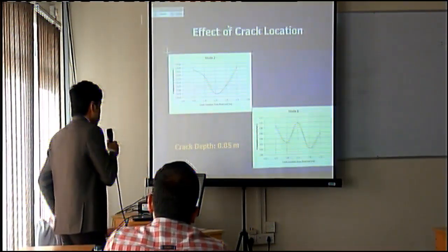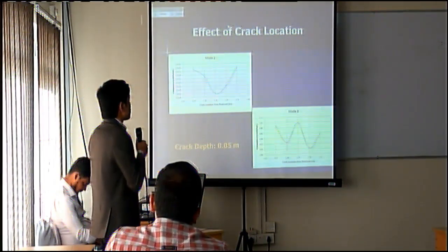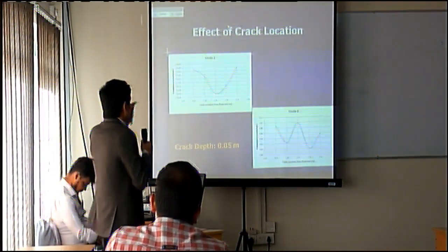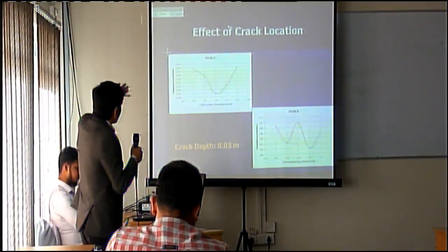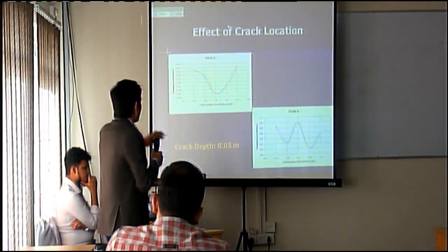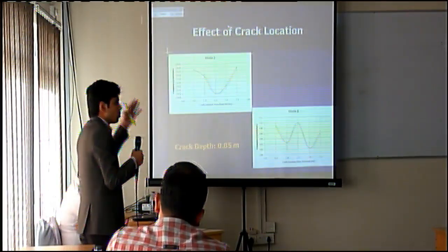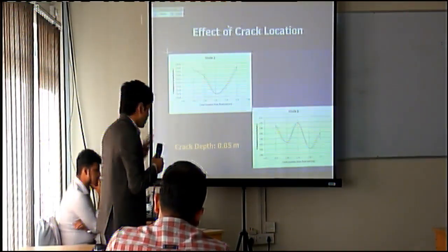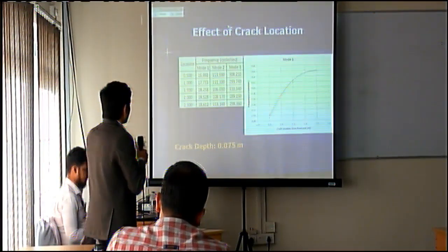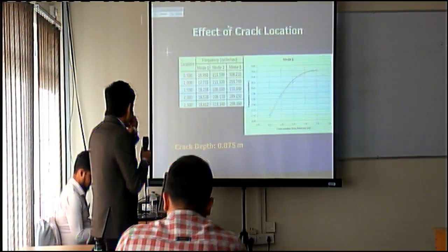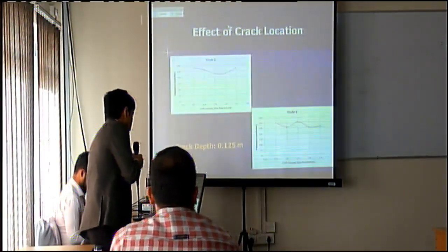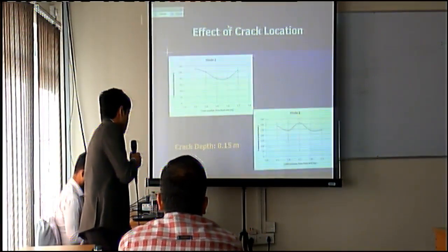Now for mode 2 and mode 3, a different pattern is found. It depends on the pattern of deflection, because the frequency reduces and then increases. The mode 2 and mode 3 show different patterns, but mode 1 all the time shows a single pattern. Same type of simulation for crack depth 0.075 meter, 0.1 meter, 0.125 meter, 0.15 meter.